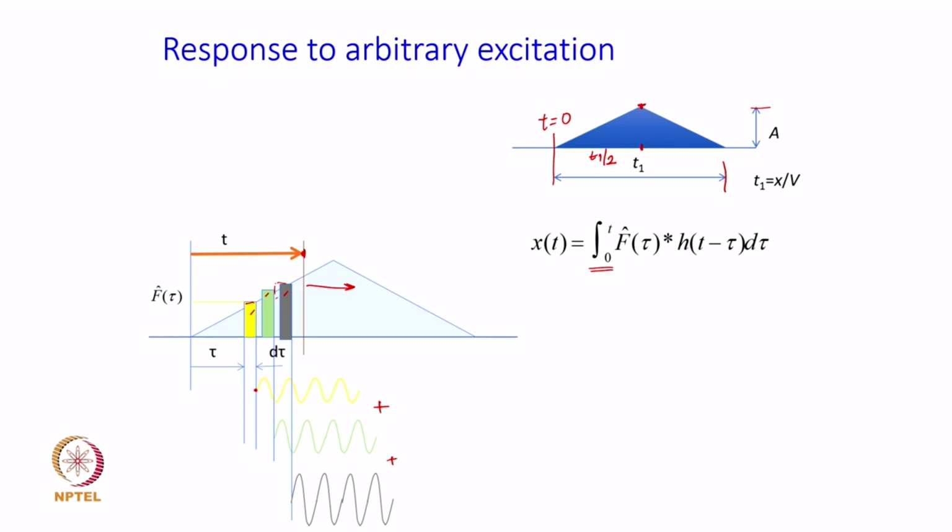Now, for that, the unit impulse response function has a very standard expression, and again we are assuming that there is no damping. The concrete columns that are supporting the mass are assumed to have no damping. So, h(t minus tau) is 1 over m omega n sin omega n (t minus tau), that is our standard expression for this unit impulse response function.